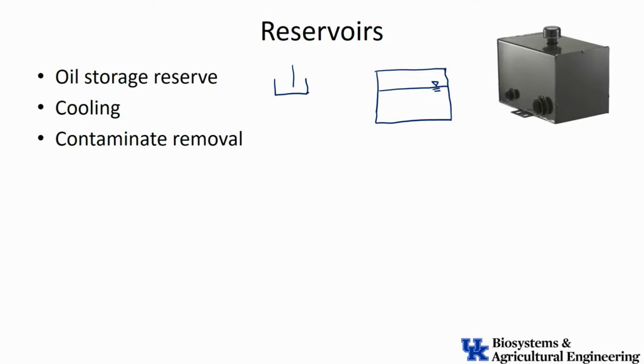So where am I going to bring the pickup? If I want to take the liquid out of this tank, go into a pump, where would I put that pickup? A lot of people think right away, hey, let's just put it in the bottom. So it pulls the fluid off the bottom, and that's going to go to our pump, all right? Is that a good idea? Not really, because what did I just say?